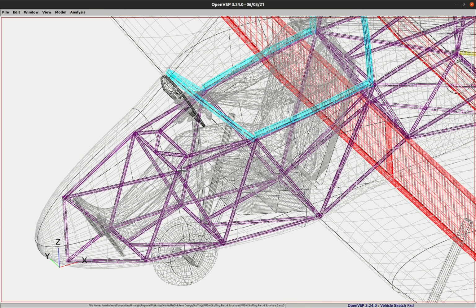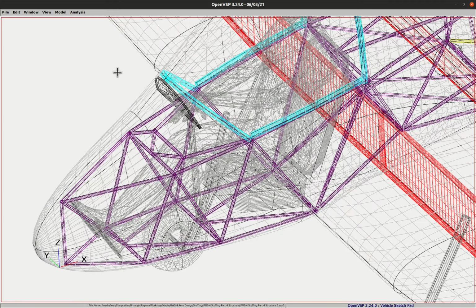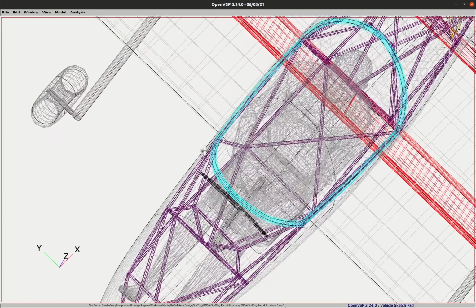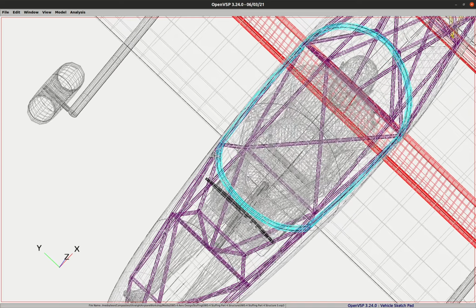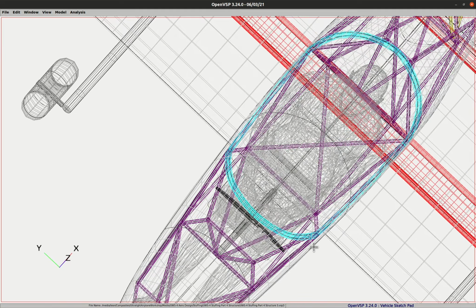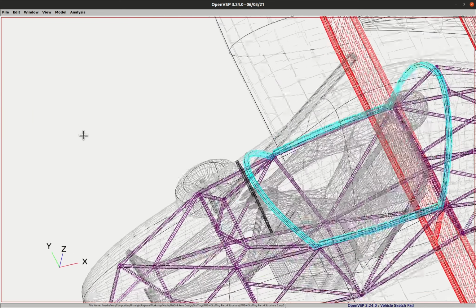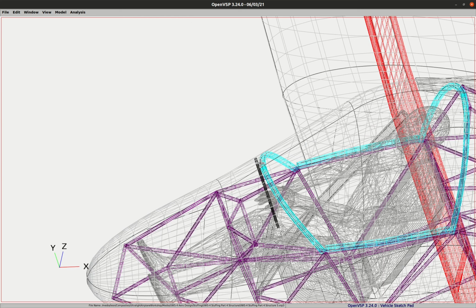Now that's okay here. I have a nice cross piece here. We have supports. This is triangular, so that's not an issue. But we have an issue here because if we hit nose first, there's going to be compression on these tubes up here. It's going to be a little bit hard to see from the top, but since we have a little bit of an outer bend here, this would try to push out and this would try to push out and try to collapse this top part. So the feet would come up, bottom would go down, and your knees would try to come up and hit the pilot.